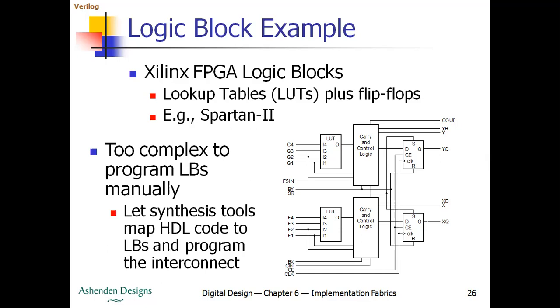In each part, we have the use of LUTs. LUT stands for lookup table. These lookup tables can accept four input data bits, for example G1, G2, G3, G4. These LUTs are nothing but synchronous RAMs, having locations of their own, and these locations are one bit wide.